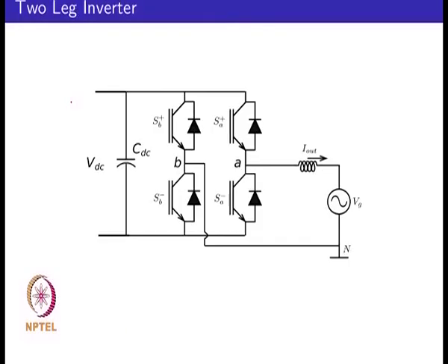If we take a single leg converter, we looked at P out and we looked at the power flow in to evaluate the DC current and the 100 hertz ripple that would be seen by the DC bus capacitors. We could do a similar analysis to evaluate the 100 hertz ripple on the DC bus.